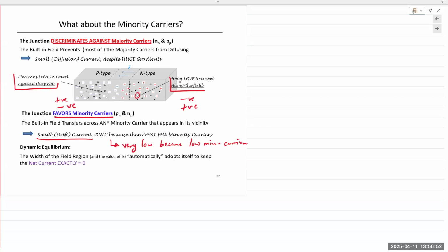The metal has plenty of free electrons, so the barrier established at the junction is very small. The lab experiment you performed, which used the BAT54, had a barrier of 0.3, 0.35 volts, far lower than silicon diodes. And the movement is very fast, so much faster speeds than a regular silicon diode.